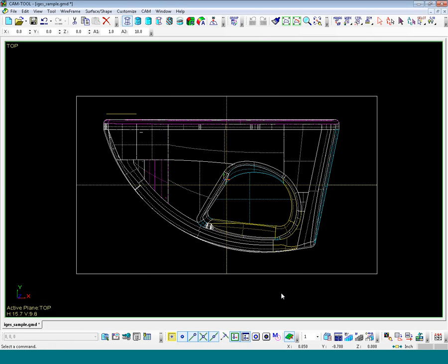For this demonstration, we're going to use layers 1, 10, and 15. Layer 1 for the geometry we want to cut, layer 10 for our stock model surfaces, and layer 15 for our calculation boundary. Now, if we want to make geometry directly on a layer, what we have to do is use this window right here. This is called your active layer. Whatever number you have in here, that's the layer number new geometry will be created on. So we've set it to layer 10, and we're going to create the surfaces we need for our stock model.